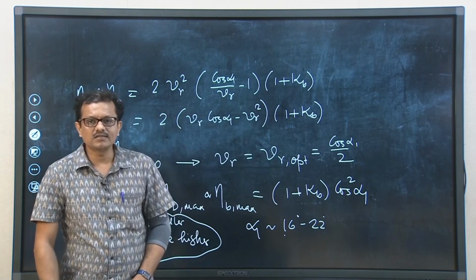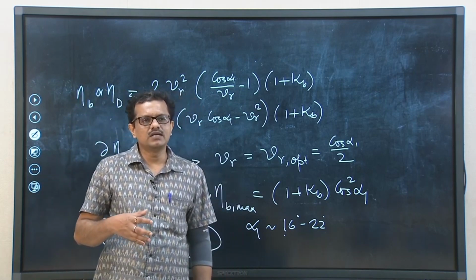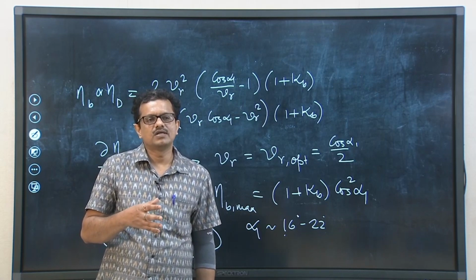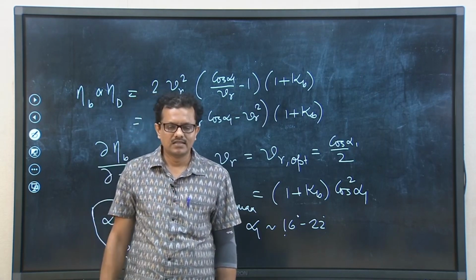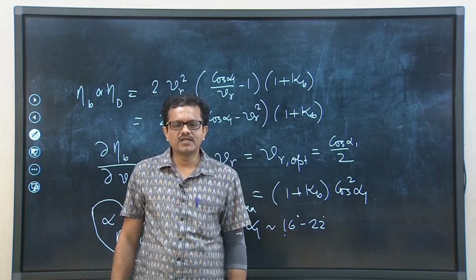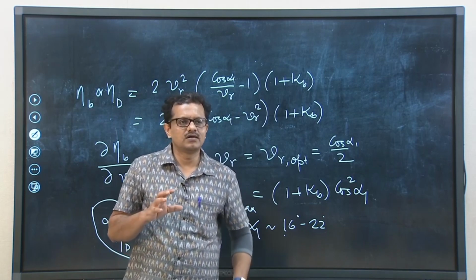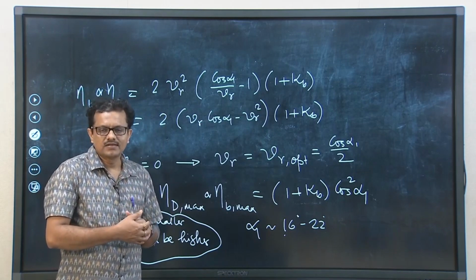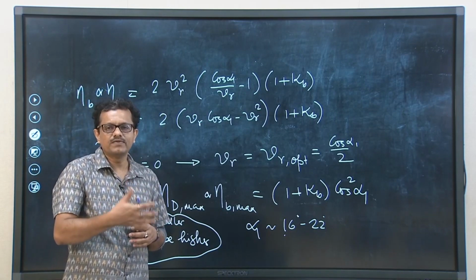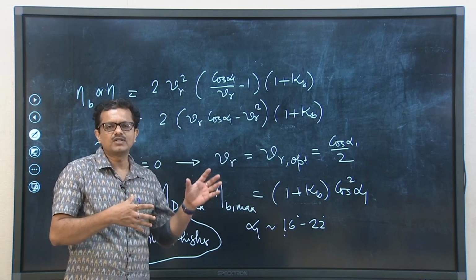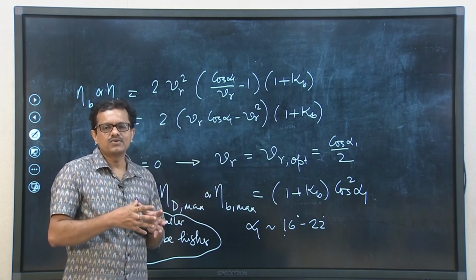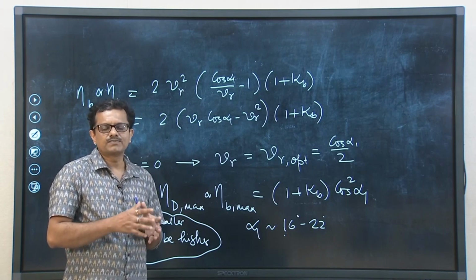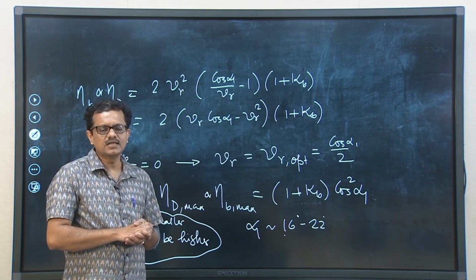Okay, to summarize today's class, we have discussed the energy transfer process inside the impulse turbine, and from there we could explain the velocity triangles. Mapping the velocity triangles on a common Vb, we have tried to estimate the tangential thrust, which is responsible for the work output, and finally we could express the blading efficiency or diagram efficiency.